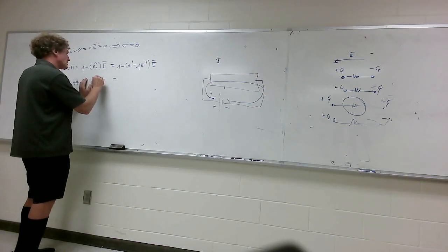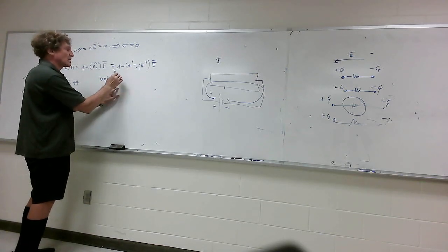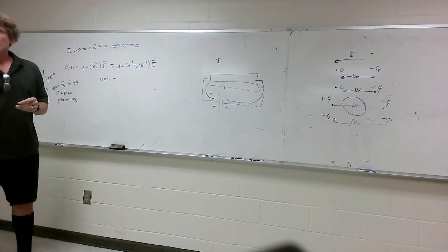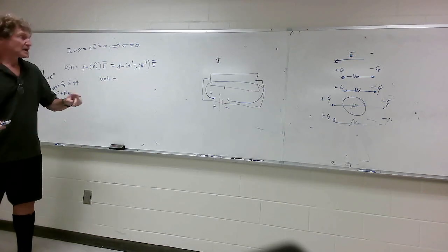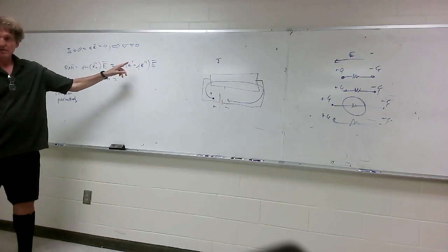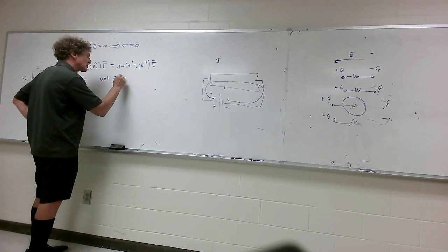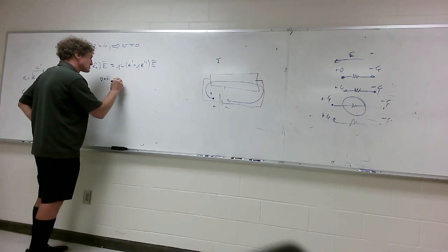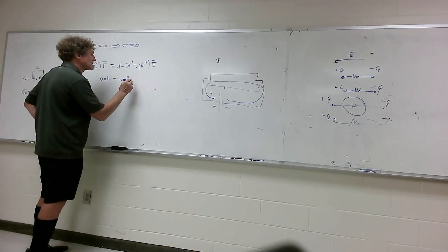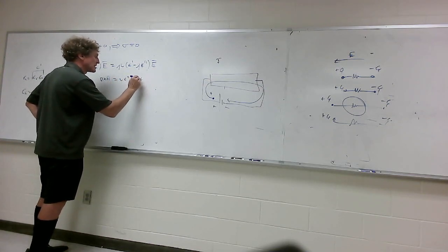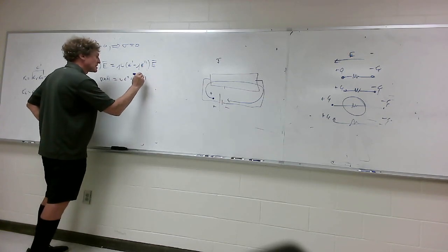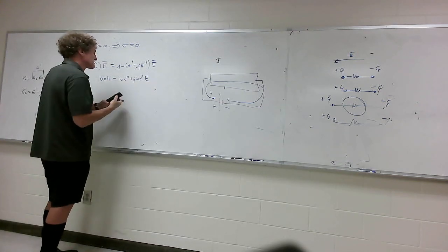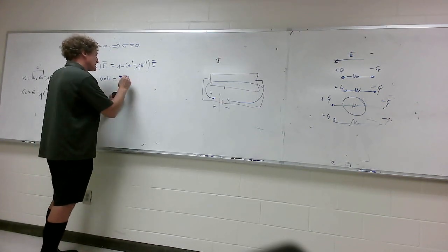I have curl of H. Now, I'm going to rearrange this, but j times j is what? j times j is minus 1, and with a minus sign it is plus 1. So we get omega epsilon double prime, and then we're going to get plus j omega epsilon prime E right here. I should say E's in both of these, pardon me. E would be here.